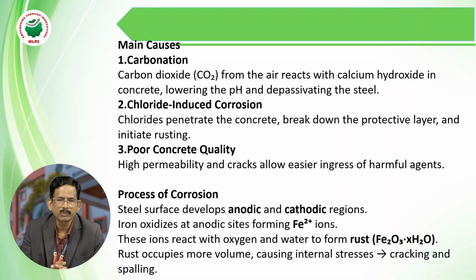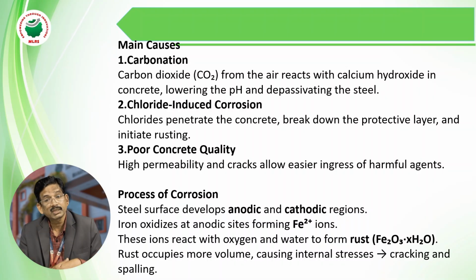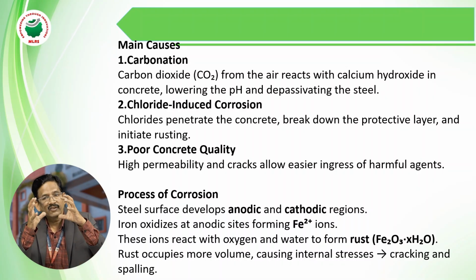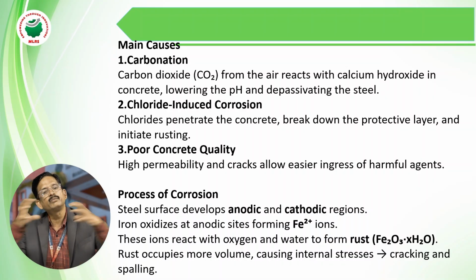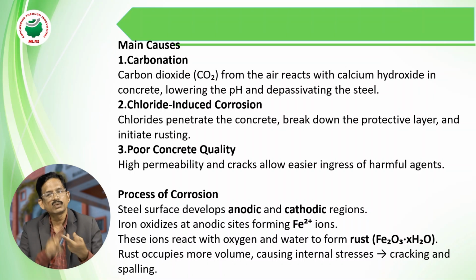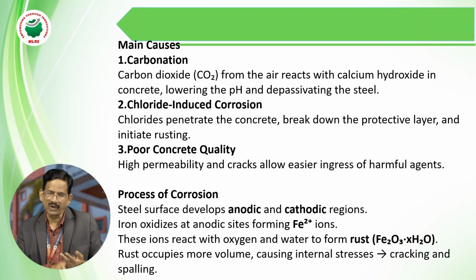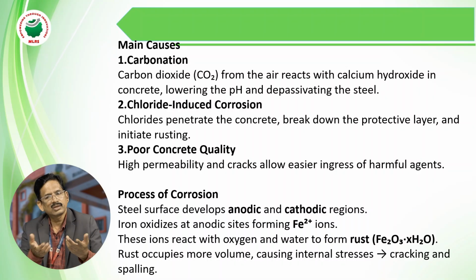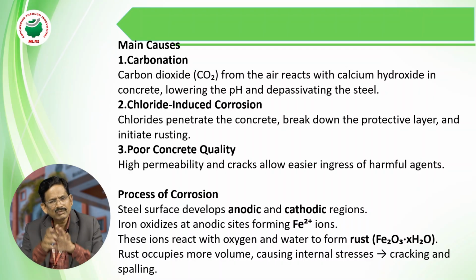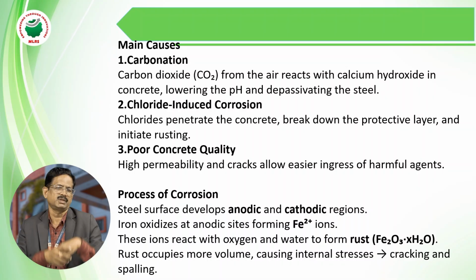But many tests are to be performed for the concrete. Why? Because concrete is a heterogeneous material. It consists of different constituent materials: cement, fine aggregate, coarse aggregate, water, admixture. Sometimes we are using substitute materials. Instead of cement, we are using cement and fly ash. Instead of sand, we are using sand and sand dust. Instead of 20 mm metal, we use 20 mm, 12 mm, 10 mm and 6 mm also. So that's why we use substitute materials.